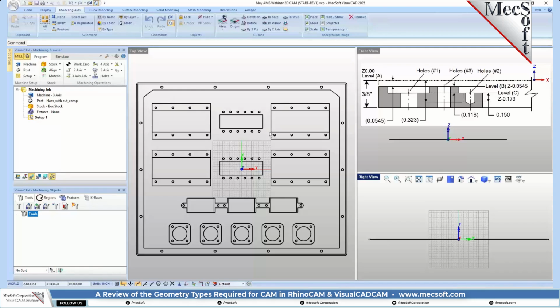If you're doing a continuous toolpath operation in 5-axis, you have 2 different types of geometry types. You have drive regions and check regions. So your drive region needs to be a surface to calculate the normal direction of the spindle, because the spindle is going to orient itself at right angles to any point on that drive surface. So that's what's going to orient the spindle for you. You can't do that with a mesh. You've got to have a surface. You've got to have preferably a NURB surface.